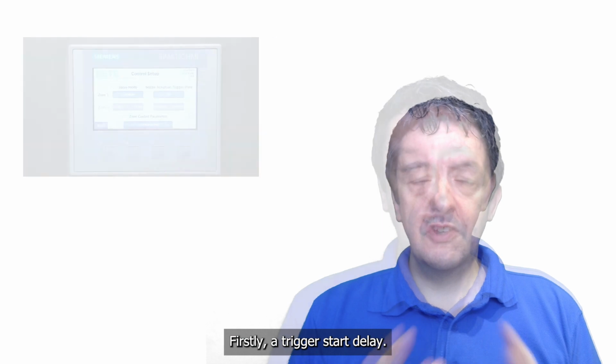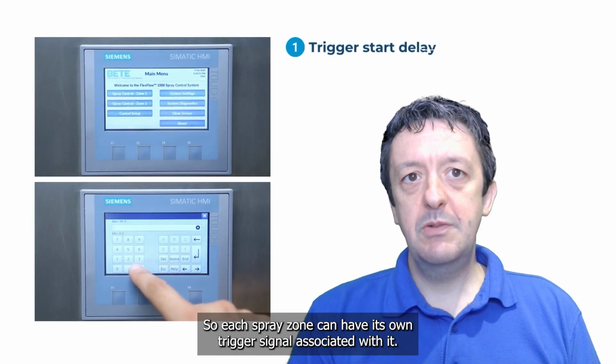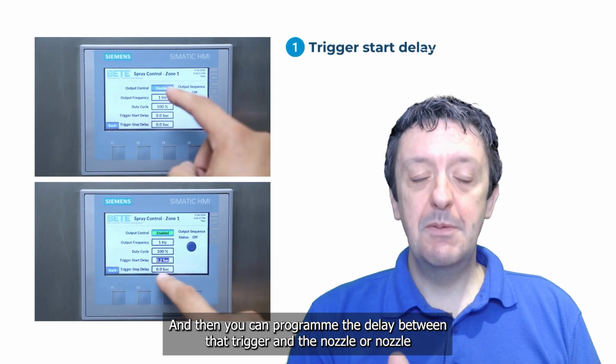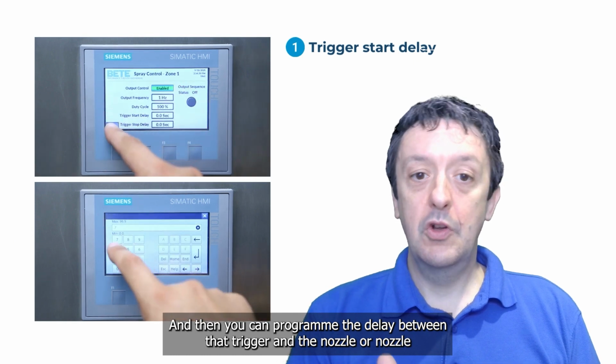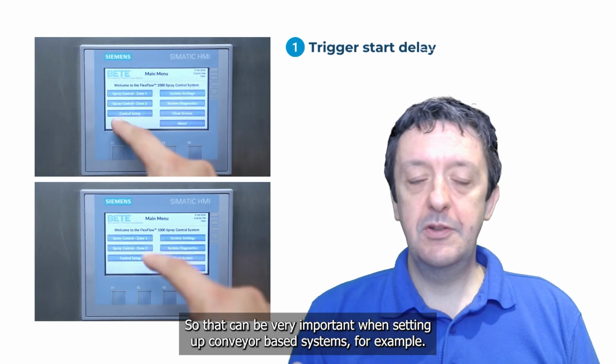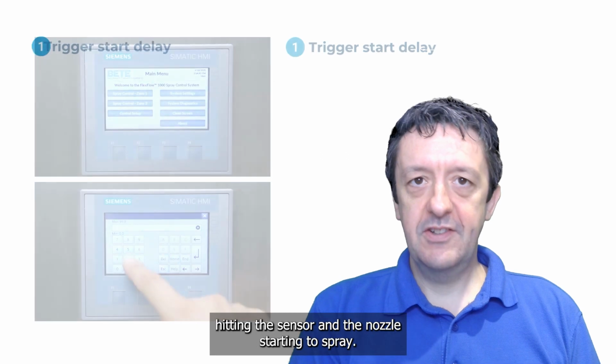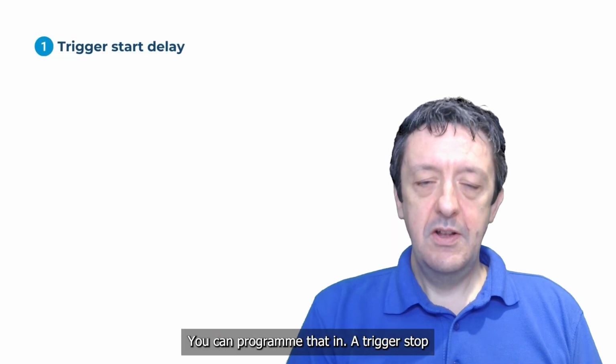First, the trigger start delay. Each spray zone can have its own trigger signal associated with it, and then you can program the delay between that trigger and the nozzle or nozzles starting to spray. That can be very important when setting up conveyor-based systems, for example. So it hits the sensor, you want a short delay between that hitting the sensor and the nozzle starting to spray, you can program that in.